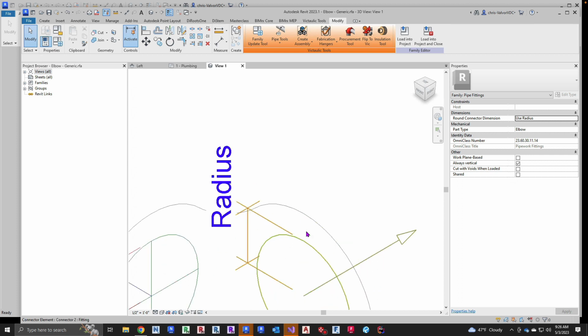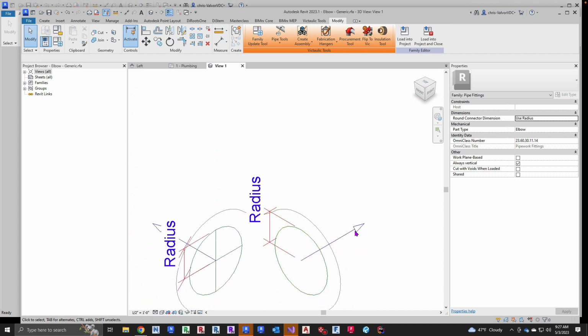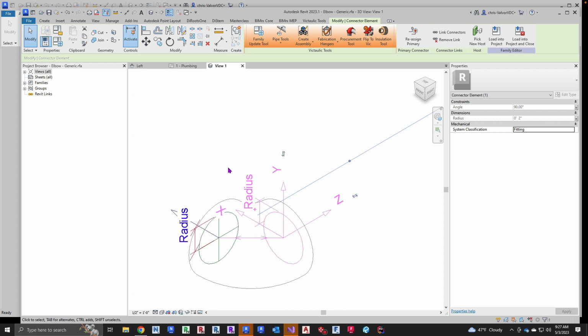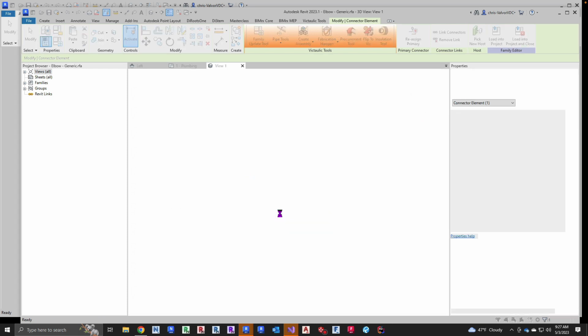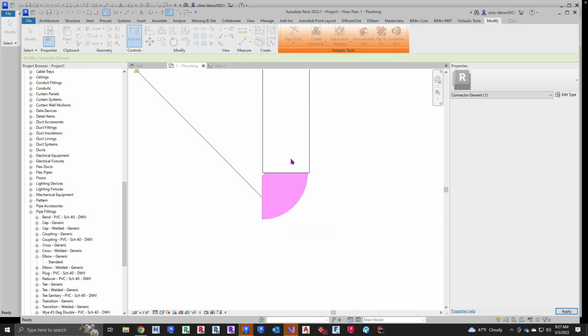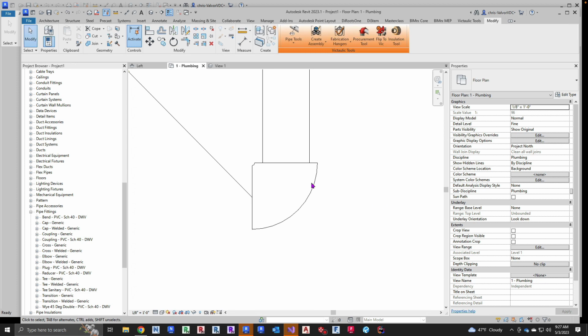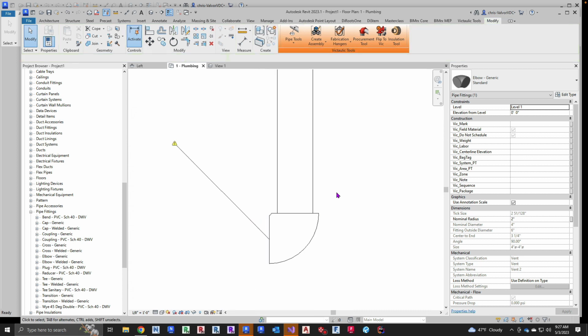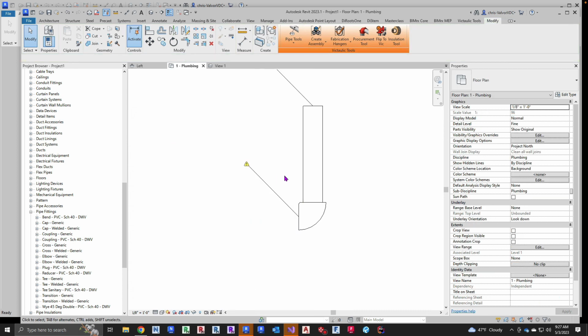Gotcha. Because you opened it. Yeah, so if I click OK, it's going to be 6-inch. This here is smaller, but this is still 4-inch here. Yep. But the piping, see the radius? It says radius 2-inch. Yep. 2 times 2 is 4. So, but the pipe is larger. And if I bring it into the model, so this is a 4-inch elbow with a 1-inch pipe.